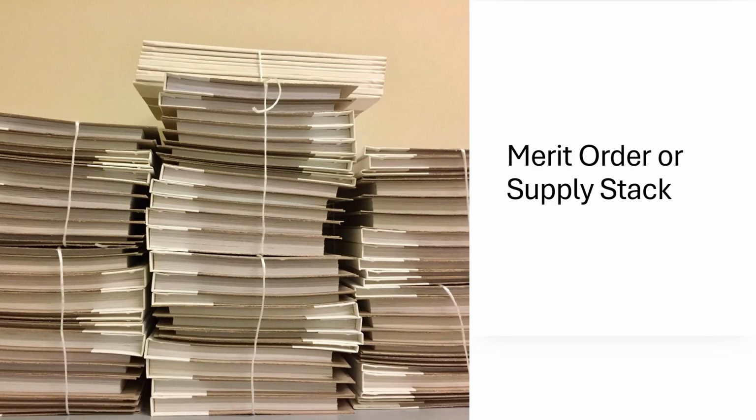Various generators bid in the amount that they would like to produce in 24 hours from now and the price that they would like to receive on a per megawatt hour basis. Now, they would, of course, try to bid in at their marginal cost, except they will bid in at zero if they want to ensure that they will operate. If they want to export electricity to another jurisdiction, they would then bid in an extremely high price, which would guarantee that they would not be taken, and as a result, they would be free to export their electricity.